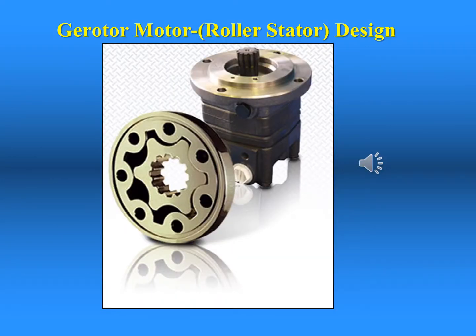A popular motor design for low-speed, high-torque applications is the gerotor, also known as the roller stator. In this illustration, you can see the two main internal components, but its operation is different from that of other designs we've looked at. The centerpiece rotates around the inside of the outer piece. This is why the motors are known for their distinct clicking noise as they operate.